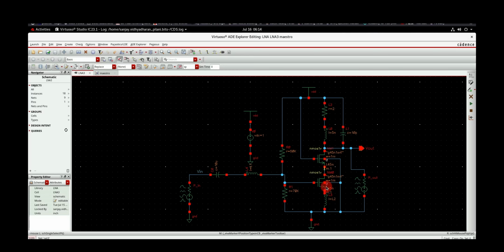If so, you might want to adjust the parameters of these MOS transistors to get back the desired performance. Most likely the gain might have deteriorated because there is source degeneration here, so this can result in a little drop in gain. To get the gain back, you can consume more power here and increase the gm of these two transistors, or use a higher transistor length and increase ro. That needs to be analyzed properly. So with this we'll end here. In the next class, if I get time, I would talk about mixers, how to design mixers and do the analysis. Thanks a lot.